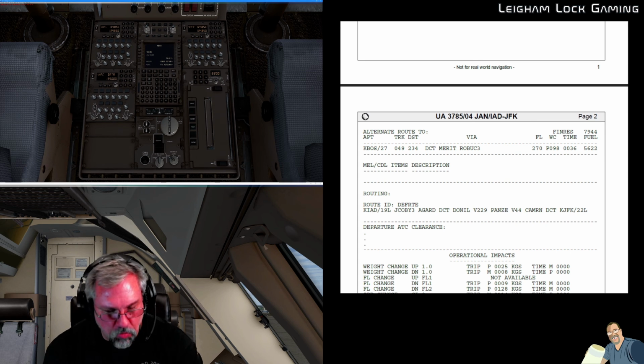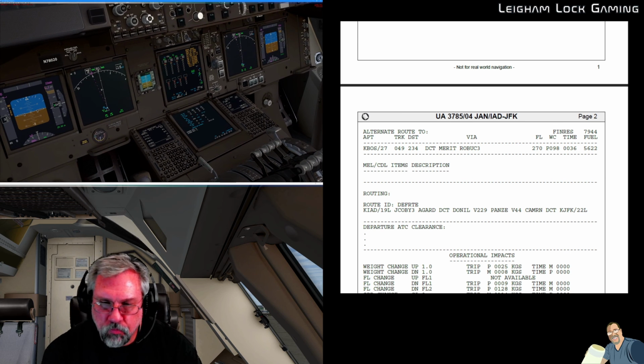Let's go ahead and go back to our FMC. We've got our Dulles departures list up, and we need to find runway 30, so we need to go to the next page. Here we have runway 30. We'll select that, and then it shows a picture of the runway actually appears on the navigation display. So that's kind of a cool reference. And the number is always at the start of the runway. So this is the direction of the runway, 30 is the start, so we'll be getting on down here to the lower part of the runway.